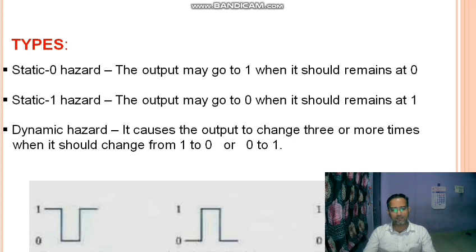The same thing for the static 0 hazard: the transition appears on the continuously propagating 0 and changes from 0 to 1. So the 0 line changes at some time to 1, a bit rises to a 1 value. That is the error that happens in static 0 hazards.